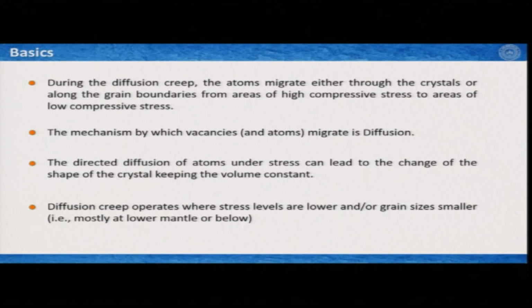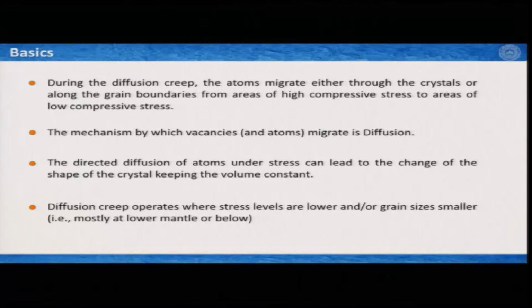Now, the directed diffusion of atoms under stress, that means all the atoms, if they are moving to a particular direction and the vacancies to the opposite direction, then this can lead to the change of the shape of the crystal where the volume remains constant.